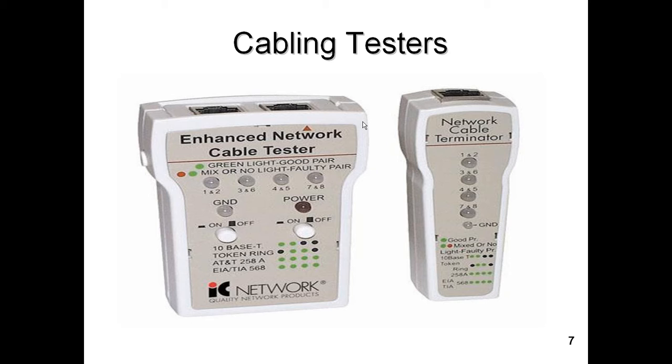That tester is going to be a two-ended tester. It can be an inexpensive one, 80 bucks or so, US, or you can spend more money if you want to. But it's going to be a two-ended tester, and here's the important point. Always test every single cable, jumpers included, every cable you're going to use to connect your devices, whether you built the cable or whether somebody else terminated the cable. Everybody makes mistakes, and often our mistakes are in the cables themselves. So you got to test every one.